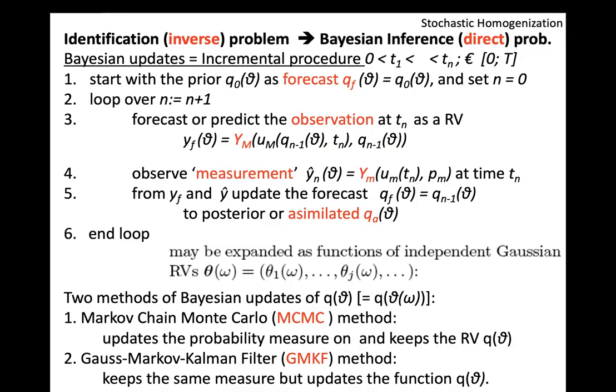Now you can turn this ill-conditioned inverse problem into something well posed if you appeal to Bayesian inference. That is, you place this mechanics problem inside a probability space, and the parameters are no longer considered deterministic, but are random variables. You try to establish the distribution of these variables, which could be parameters of a problem, for example Young's modulus, yield stress, and so on.